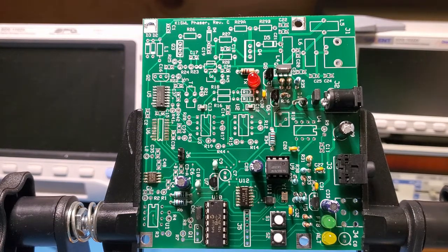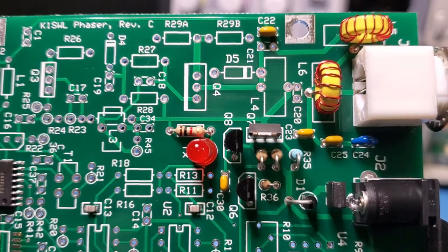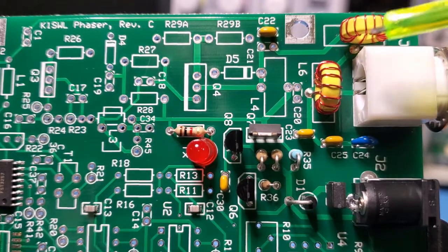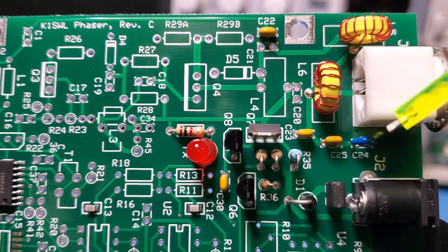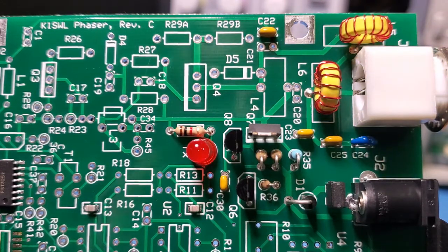So I'll pull this all together, and then we'll inject some test signals here and see what's what. Okay, so here's the finished low pass filter section. The two toroids here, L5 and L6. Nothing special about winding the toroids. Direction doesn't matter. Conductivity does matter, and we'll check that later. But just double check the values of each of the capacitors. Obviously, they're critical. I've also installed the BNC.